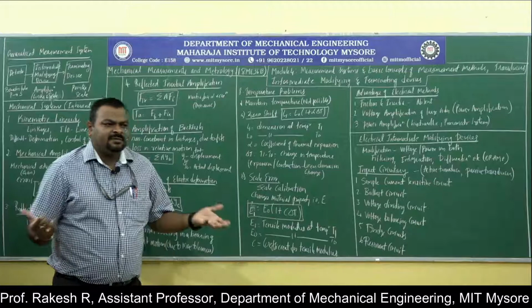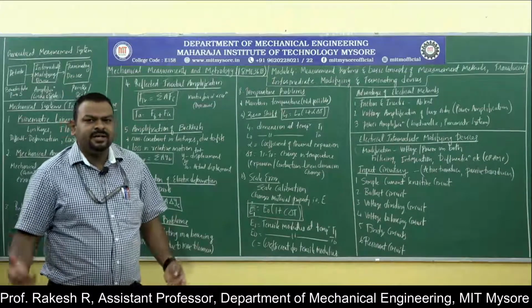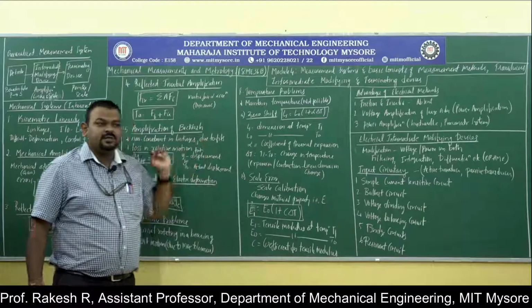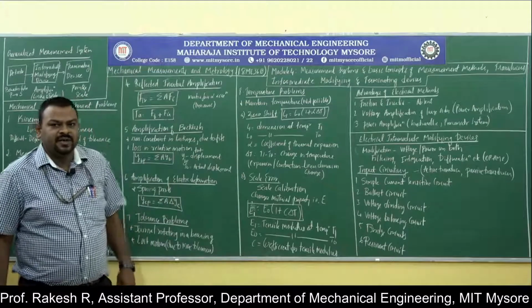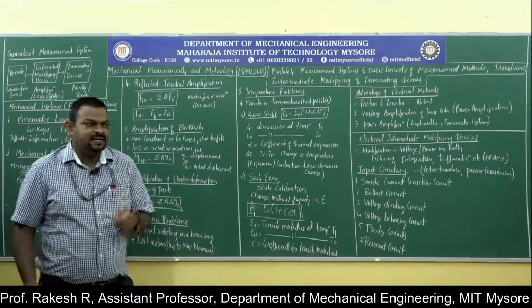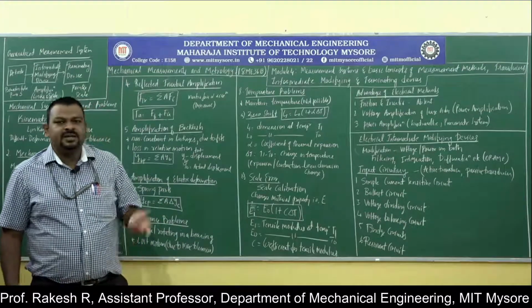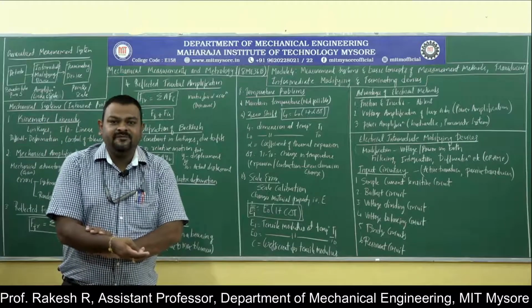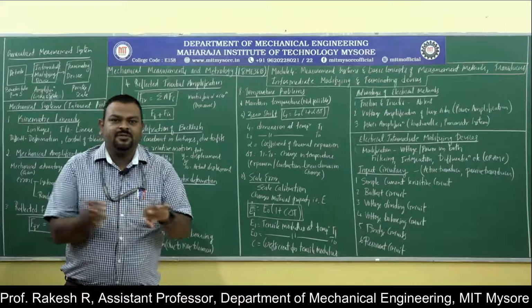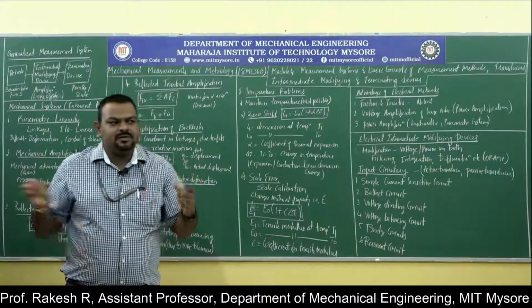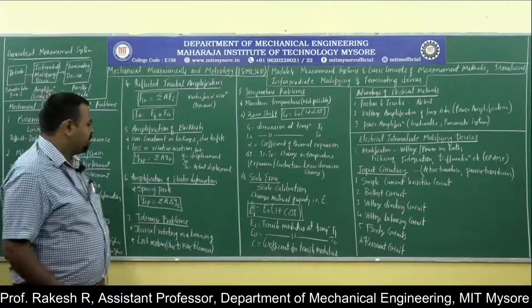There are several fits: clearance fit, interference fit, and transition fit. And you know how to select those fits depending upon the requirement. If there is no force, clearance fit. If there is a force, it is an interference fit. Sometimes we need both. In those cases, you will be using a transition fit, where pressure is also involved, force is also involved. Pressure or force, the same will be involved. Also, it will go as usual.